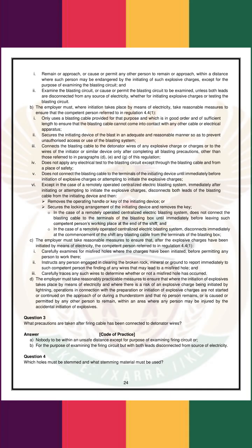In the case of a remotely operated centralized electric blasting system, does not connect the blasting cable to the terminals of the blasting box until immediately before leaving such competent person's working place at the end of the shift, and disconnects immediately at the commencement of the shift any blasting cable from the terminals of the blasting box.